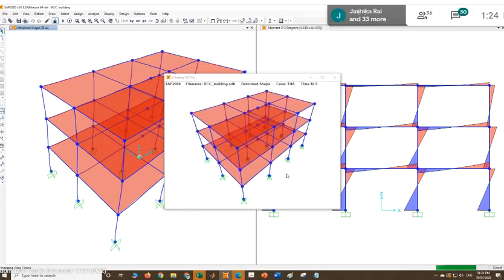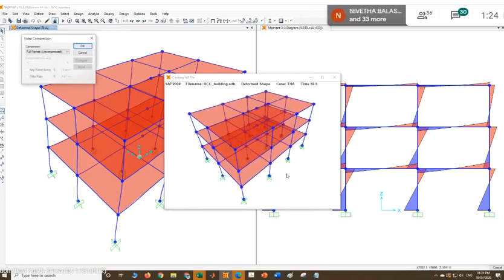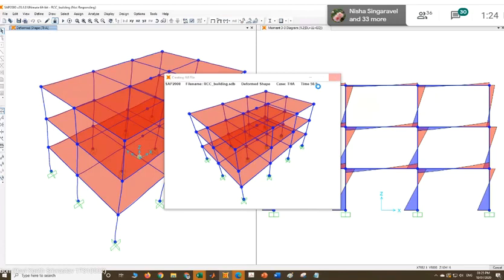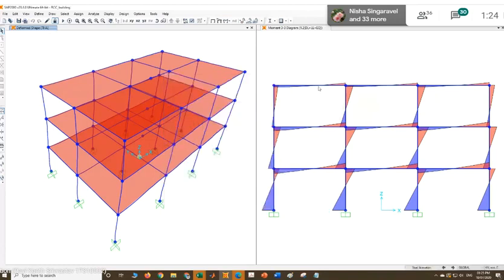Okay, you saw that, right? So we can save that also. See, this building after the analysis is also in a very good shape. Why? Because we have not assumed that any non-linearity is going on, because of which after each instant of time it is returning to its initial shape, and then again analysis is being carried out, right? So this is how we need to carry out time history analysis. I have not gone to non-linear. Maybe in future we can meet, and if somebody wants to know more about non-linearity, I can explain.